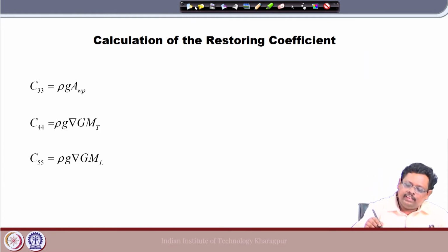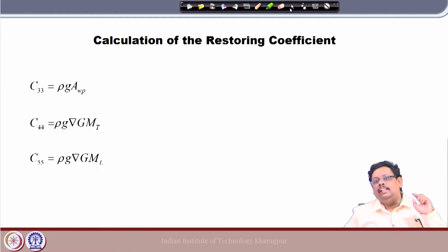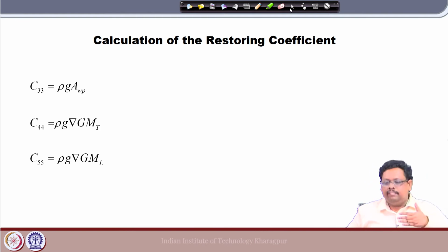So, out of these 6 modes of motion, there are 3 modes where there is no restoration. However, if the ship is heaving, that means going downwards, then of course there is a buoyancy force that pulls it up, so it experiences a force.